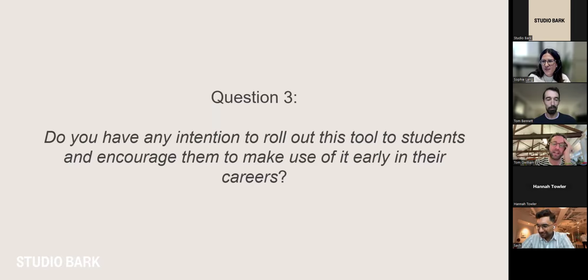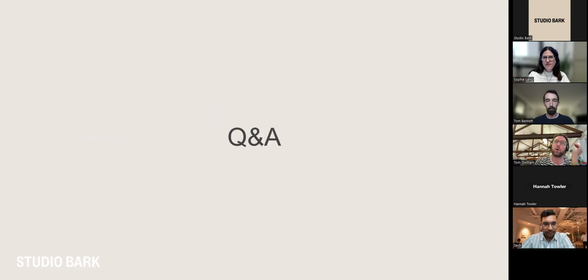Yeah. So essentially, yes. It would be fairly simple to create a U-value calculator, because what the build-up calculation is doing already is basically a U-value calculation. You see a similar thing to what you might get in PHPP or other energy assessment tools, and it even looks a bit similar to what the BuildDesk option is. So for those familiar with U-values, it looks very familiar. The thing it's missing obviously is the thermal resistances of the materials. So it depends on the appetite for adding that into the library and having a user option for it as well.